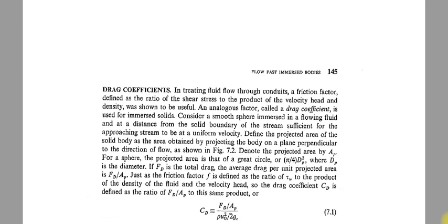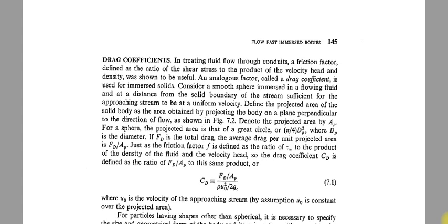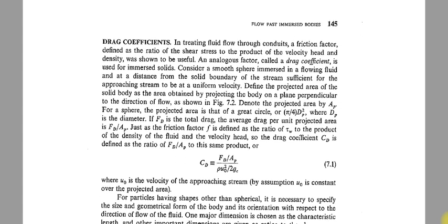Now we will discuss how to calculate the drag. Similar to the friction force or the shear force in the closed channel, we can also calculate the drag by using a coefficient that is called the drag coefficient. In the closed channel we discussed the friction factor. Similar to the friction factor, we define here one coefficient, CD, the drag coefficient. So CD is equal to FD divided by AP divided by rho u square by 2.